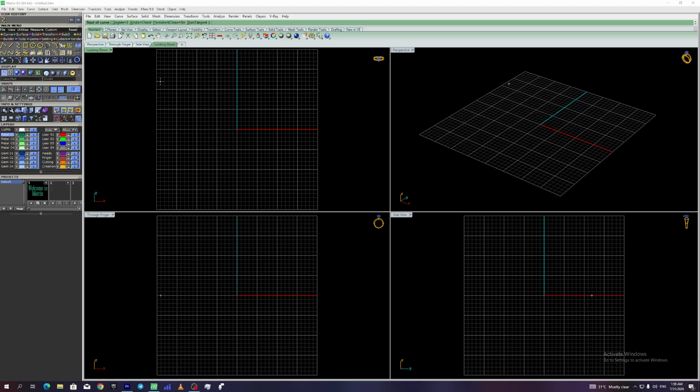When you click on the Interp Curve command and set your starting point, for example using F4 to start from the center, you can begin clicking around the screen to create a flowing organic curve. Each click adds a new point and Rhino automatically draws a smooth curve that passes through all of them.